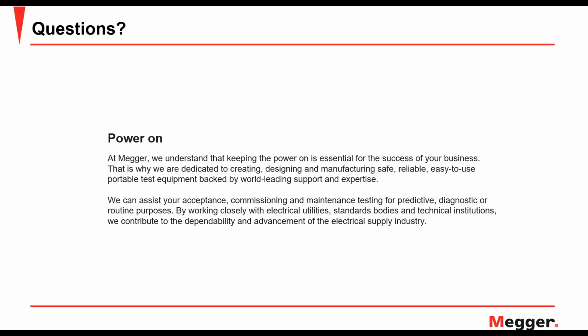It's up to you. The IEEE makes recommendations, but you want to at least make sure that you have the in-service tap position measurements, because this is all about site reference, right? So you want to make sure you have your reference test results in place. If your transformer is going to be operating at a certain tap and that tap position is not going to change much over the years, then you want the reference test results for those tap positions.